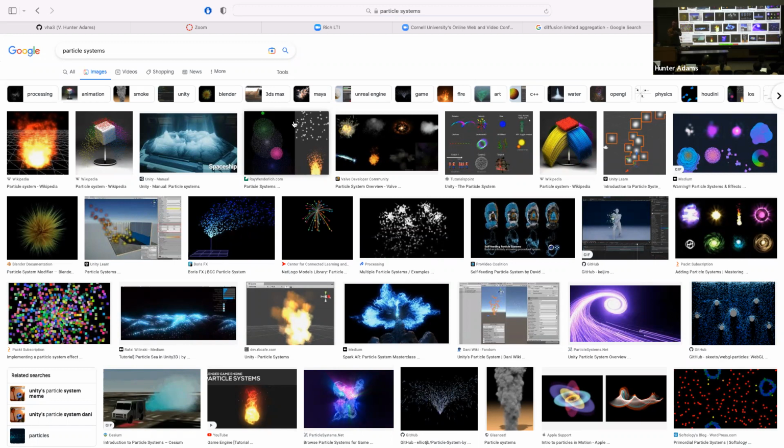In fact, if you watch the old Star Wars movies, those in-space explosions, I believe, are all particle system simulations. And then the other thing that you can play with is have the color of the particle also be a function of its position on the VGA screen. So you can imagine, for instance, spawning tens of thousands of particles down at the bottom of the VGA screen and generate some vector field that sort of approximately goes like this, and then change the colorization so that they go from maybe white or blue up to orangey up to yellow, and you could generate a beautiful candle flame. And then maybe make a breeze go across the screen so that the candle flame goes like this.